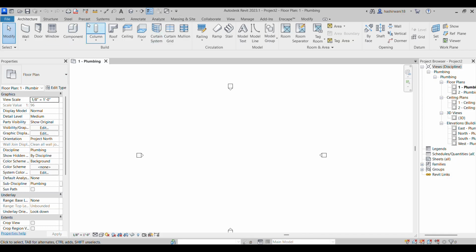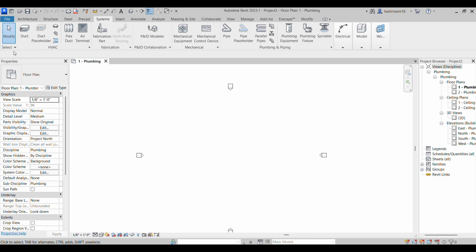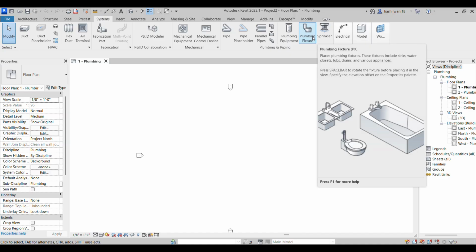So for my plumbing, I can go to the systems tab. I have different sorts of MEP units, MEP systems here. We have HVAC system, we have fabrication, we have mechanical, we have plumbing, and we have electrical here as well. For this particular video, this is a plumbing masterclass, and we're going to be focusing on plumbing and piping. So we have a plumbing pipe here, we have a pipe placeholder, we have pipe fittings, we have pipe accessories here as well, we have some flexible pipes just like flexible ducts here, we have plumbing equipment, we have plumbing fixtures which are our water closets, etc. Can you see sinks, water closets, drains, and showers, etc.